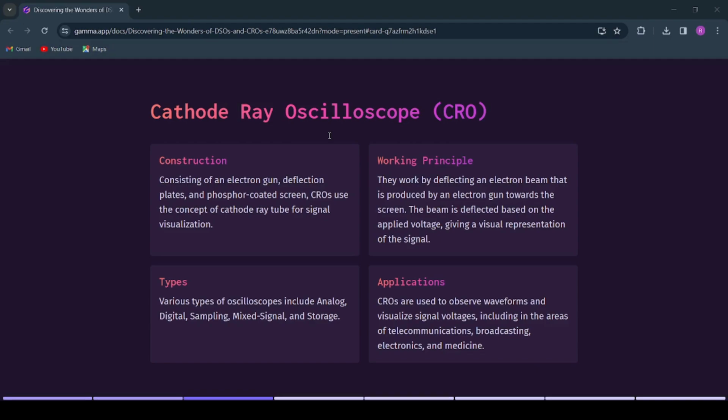The horizontal voltage moves the luminous spot periodically in a horizontal direction from left to right under the display area or screen. The vertical voltage is the voltage under investigation. The vertical voltage moves the luminous spot up and down on the screen. When the input voltage moves very fast on the screen, the display on the screen appears stationary. Thus, CRO provides a means of visualizing time varying voltage.